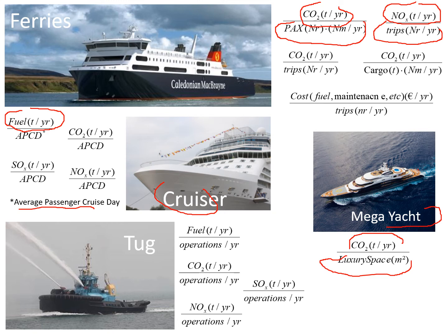And of course, when we are talking about power drivetrains, we need to see how our power drivetrain design is affecting these emissions, for example, or affecting the space on board. If our propulsion system is bulky, if the electric machine and the electronics are so big that we do not have any space left on the vessel for passengers or goods, that means we are making our criteria worse. So our power system is not competitive, because maybe our competitors have a more compact system than what we have.